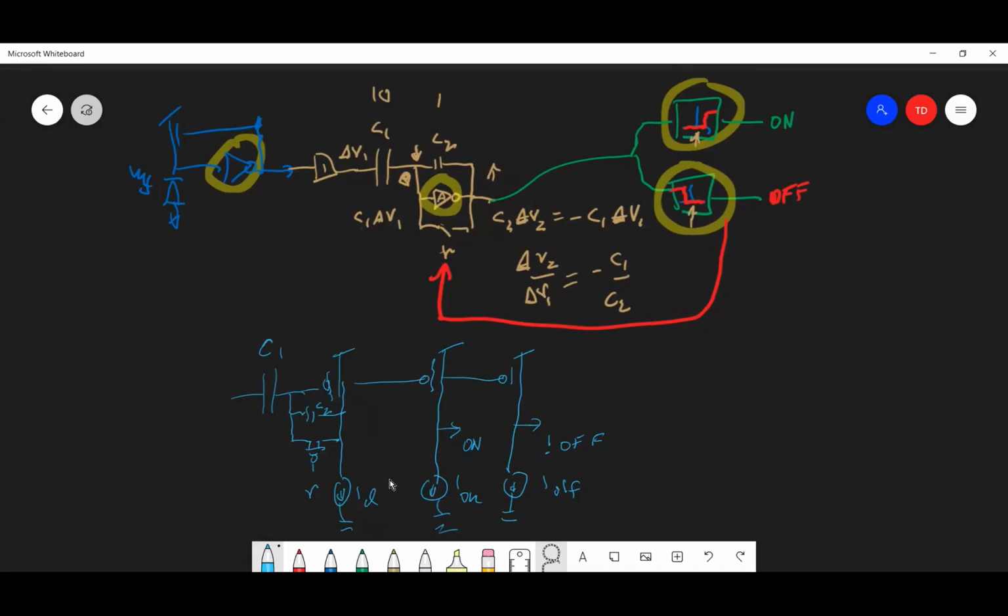In fact, the threshold voltage here is proportional to the thermal voltage if these currents have a constant ratio. In other words, if I on is 2 times bigger than ID, independent of temperature, then the threshold voltage is actually proportional to the thermal voltage. But this output voltage here is also proportional to the thermal voltage. So therefore, it turns out that the threshold for log intensity change is independent of temperature. You think about that a little bit.